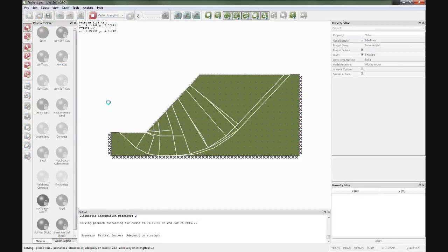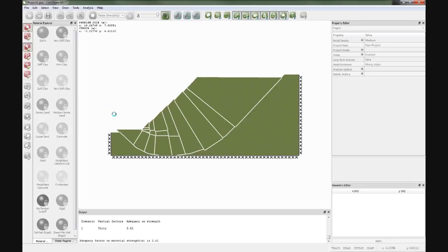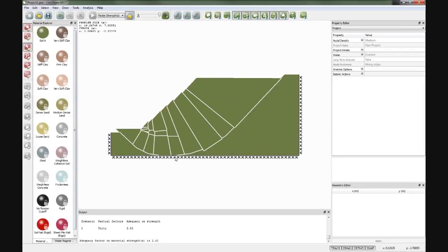Now, for those of you familiar with this type of analysis, you'll realize we're onto a sort of road to nowhere here. I can keep pulling these boundaries out forever, and for slopes that are shallower than this angle, or this angle, the actual critical mechanism is effectively of infinite size, but the factor on safety doesn't change that much. So if I kept pulling those boundaries out, the mechanism would just grow and grow. And that's what you see from the Taylor analysis also.